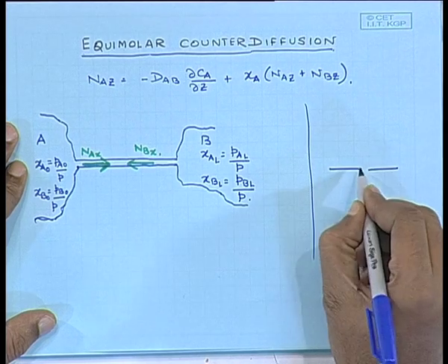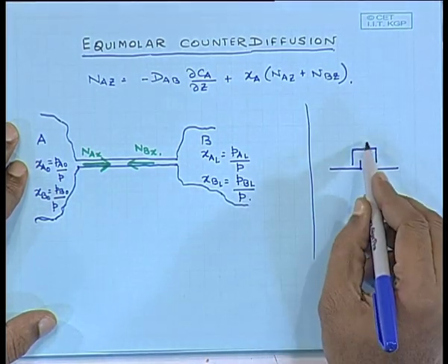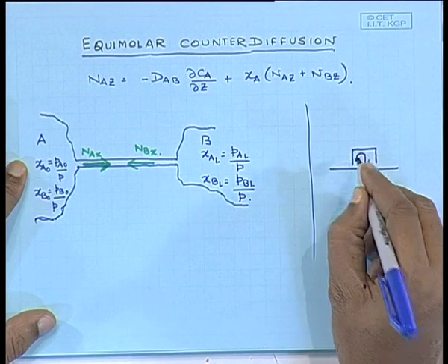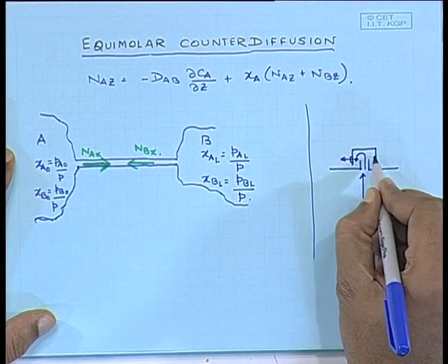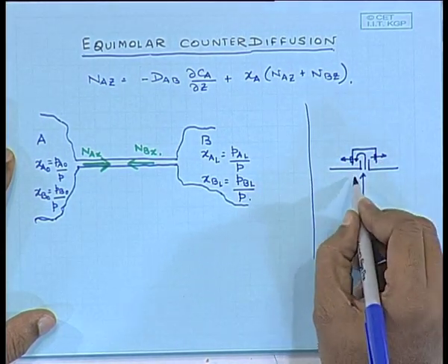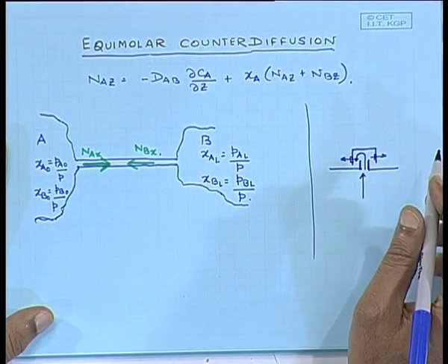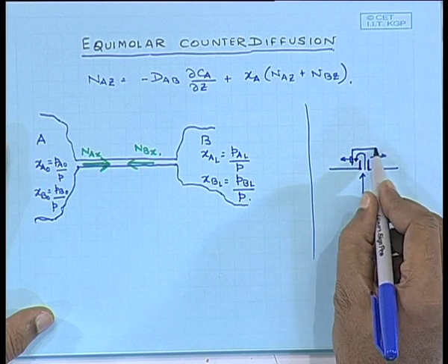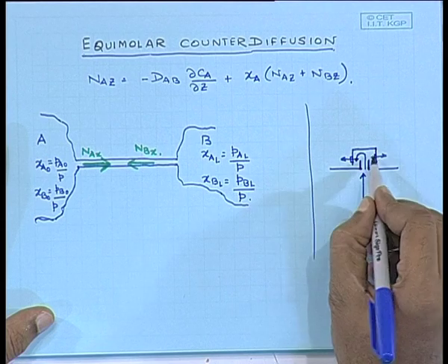So, as the name suggests, if I look at a bubble cap, if this is a solid tray, then an arrangement like this is provided. So, this thing is known as a bubble cap. The gas which comes through this will have to change its direction, and then there are openings here which are known as slots. The vapor will come out of these slots, and this portion and the clearance, there are several considerations which will help one design what would be this height, what would be this clearance. This is a skirt. So, what would be this clearance, and many things will govern these things,